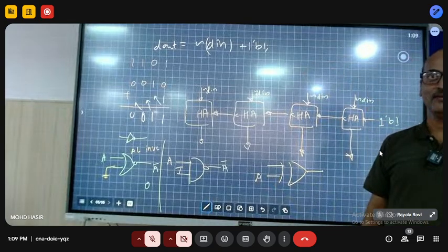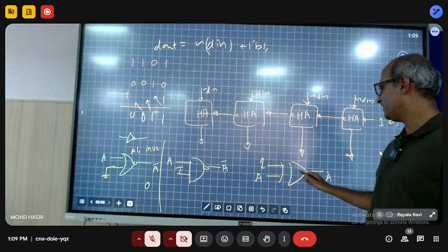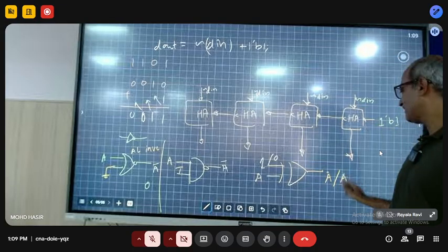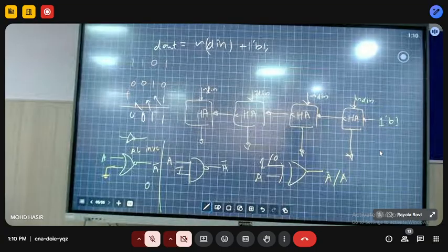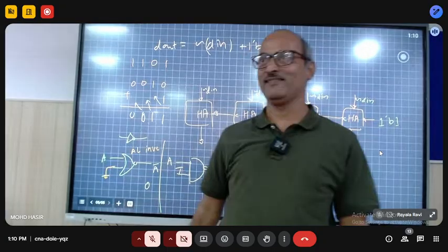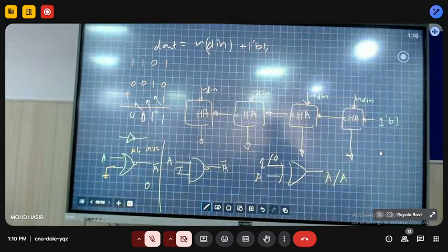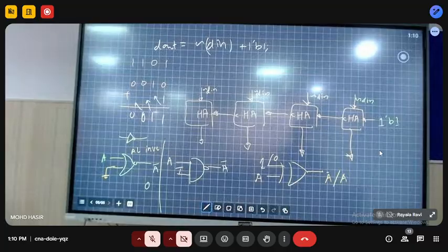This is active low inversion here you want to do. If your interest is to invert the design output with active low enable, so you can say inverter with active low enable signal. How about this? Inverter with active high enable signal. Right? Agreed? So now you have added programmability. Either you want inverted output or not. Under one circumstance, one will give output always equal to 0, the other will give output always equal to 1.